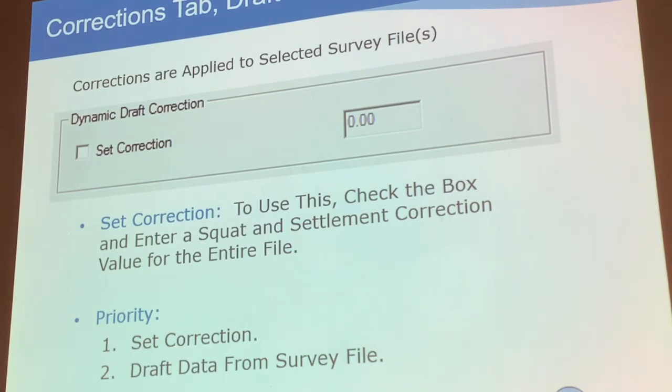So how you measure it is before you do your survey, someone must stand at the shore, right? And then you use a total station, and you hold a reflector on the boat. When the boat is moving, you take one height, and then once it's moving, you take another height. You can check the difference in the draft through that height difference.